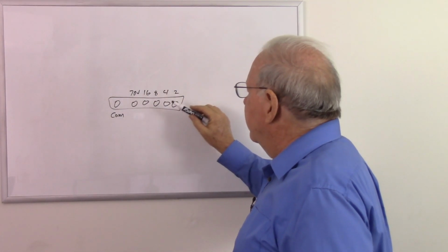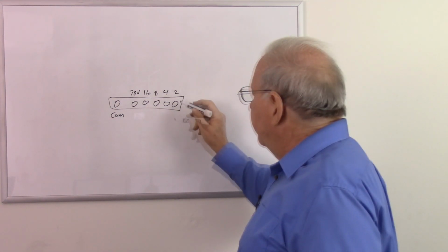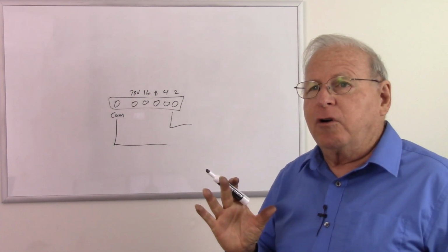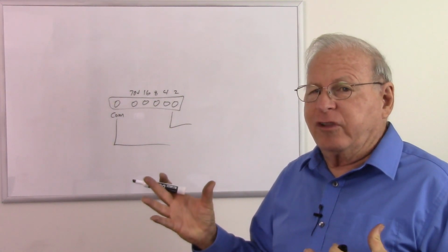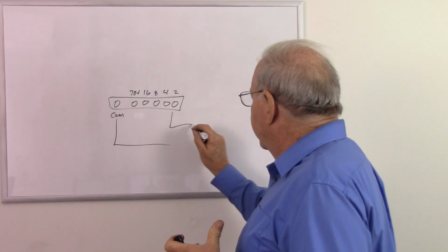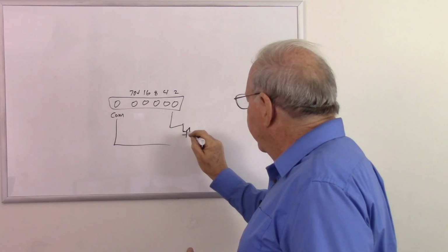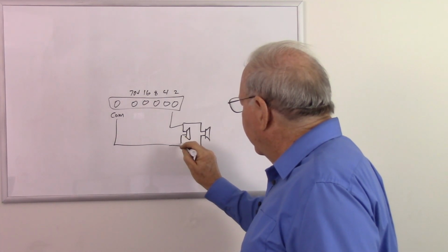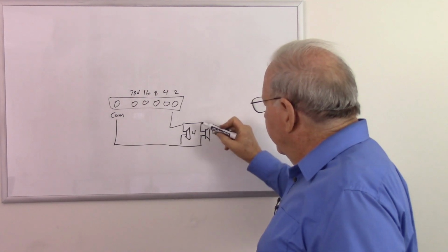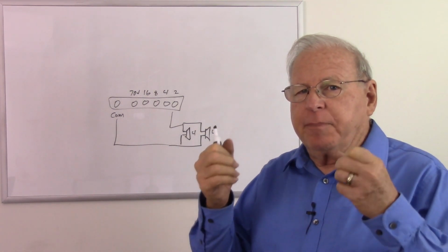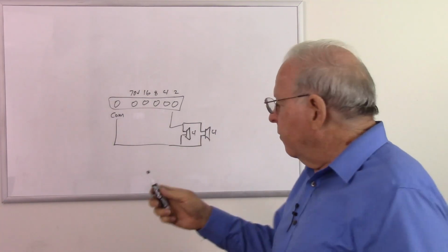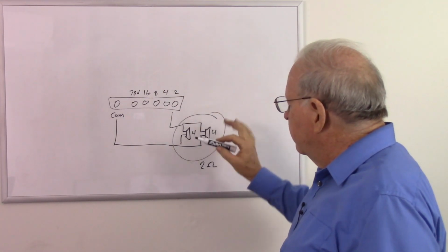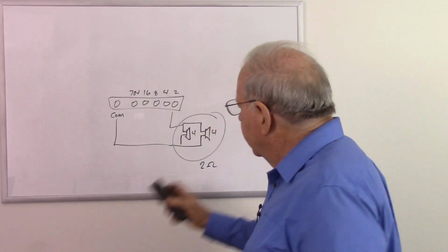But in this case, we can talk about it because we can figure out what we can do. If we have a 2 ohm output, so we're coming from the common, and the 2 ohm, what does that mean about our speakers? We need to have a combination of speakers that gives us 2 ohms. You can buy raw speakers that have impedances of 4 to 16 ohms. So let's say we have 2 4 ohm speakers, I'll put one here and one here in parallel. So these are 4 ohm speakers. 2 4 ohm speakers in parallel will give us what impedance? Remember, if your impedances are in parallel, if they're equal, the total impedance is half of either one. So together that's going to be 2 ohms. So that 2 ohm output would be for some combination of speakers that gives us 2 ohms, which this would give us. And of course the 4 ohm output could go to that 4 ohm speaker.